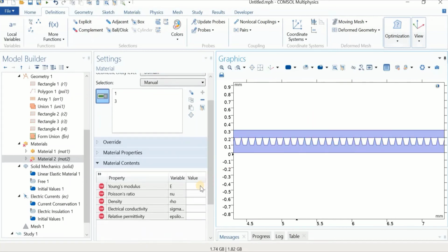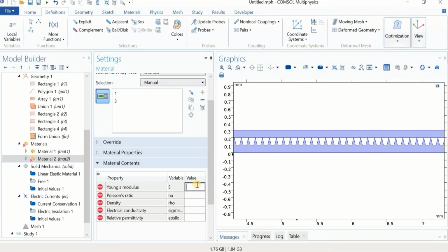And then in the Young modulus, as I said, I'm gonna use a relatively elastic material. So I'm gonna use 2E7, right? And for the Poisson ratio 0.4, it mimics some sort of relatively flexible polymer, but in fact it's not one single polymer.